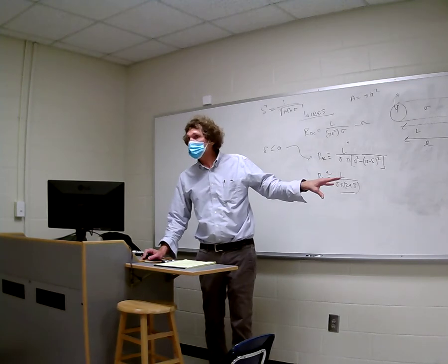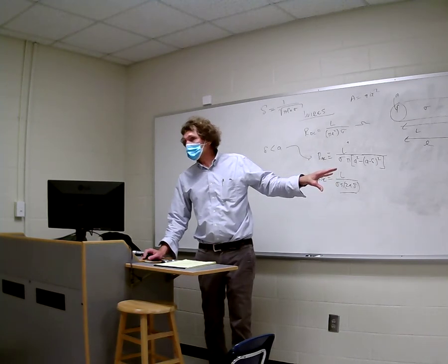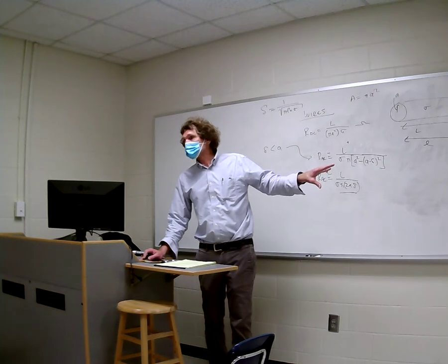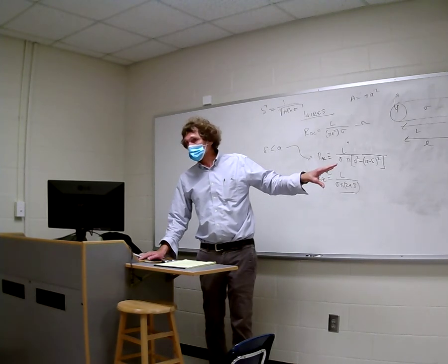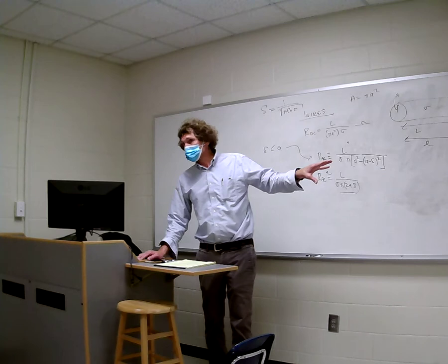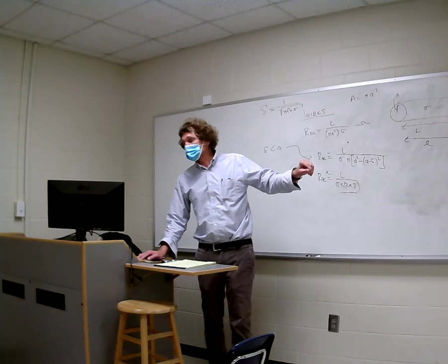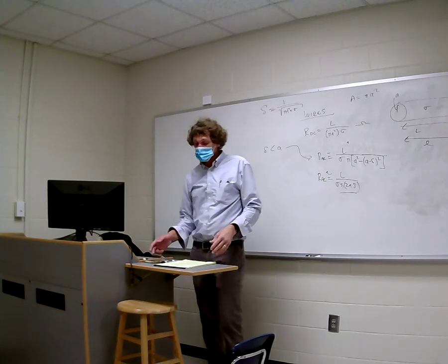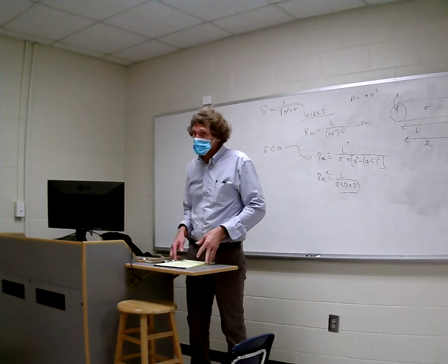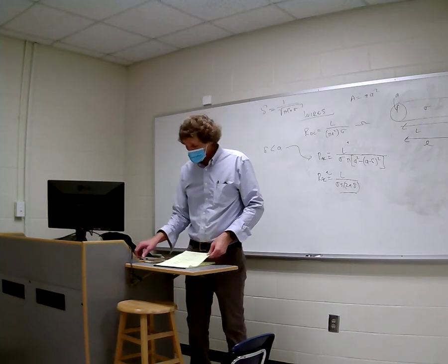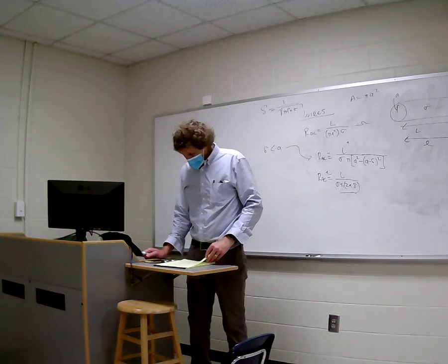That's a formula. Just understand it comes from theoretical work that's based on some approximations of straight wires. How well it works, honestly, I'm not sure. I've never used it. Everything I've done, if I need inductance, it's either measured or it uses a piece of software to do an actual solution of Maxwell's equations for the environment. Okay,